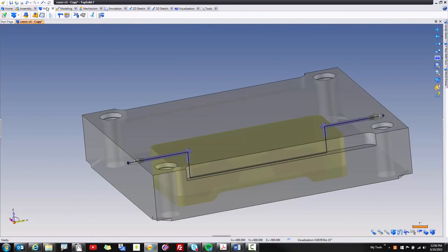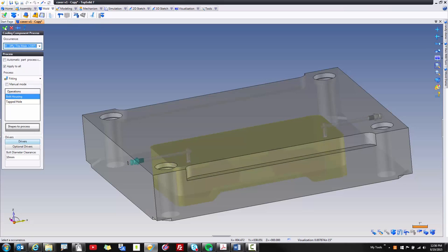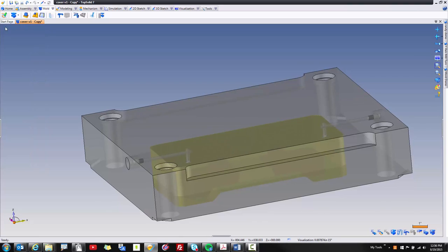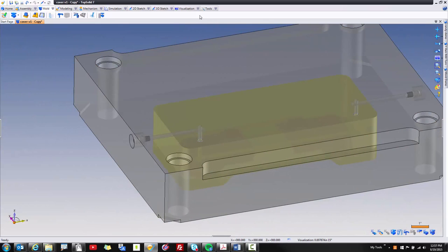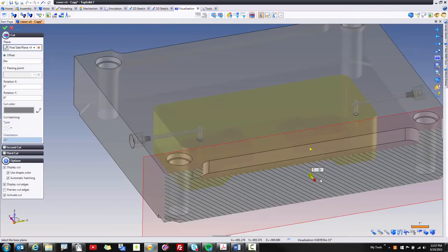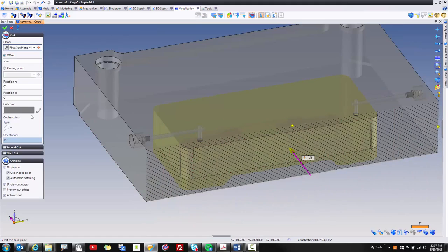The last step is to go back to the mold process here and process the cooling circuit. Go ahead and validate. And now the software is going to automatically process each component. And if you look, there's the counterbore for your pipe nipple. Moreover, let's maybe use the visualization tool here. Let's cut a section here, and maybe I want to look right down the center line of that.